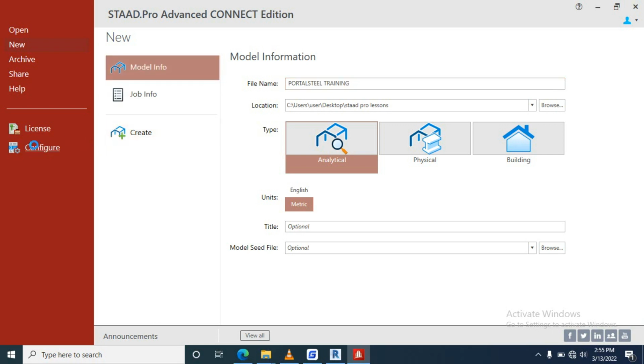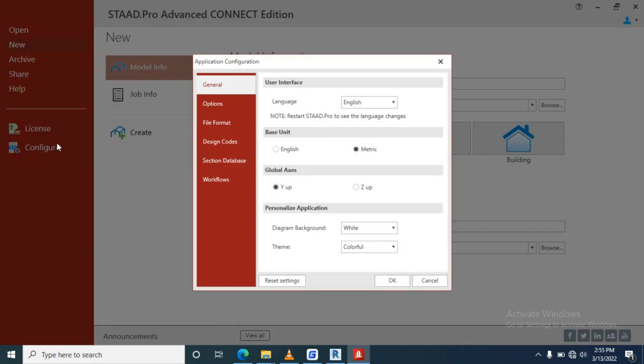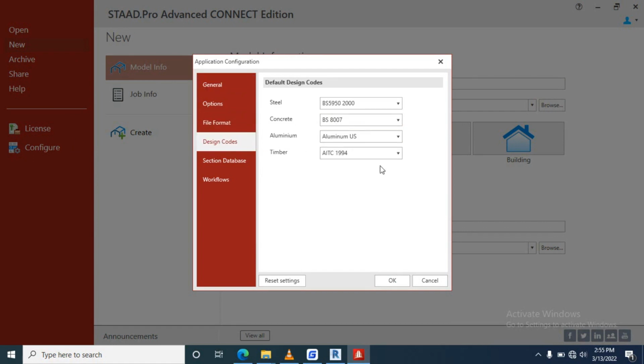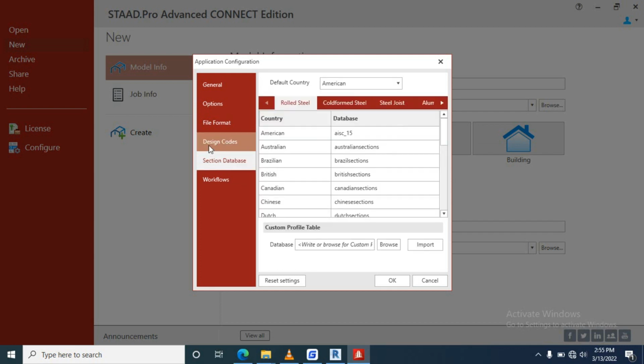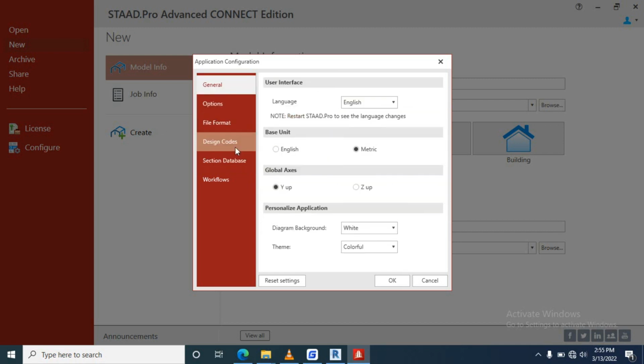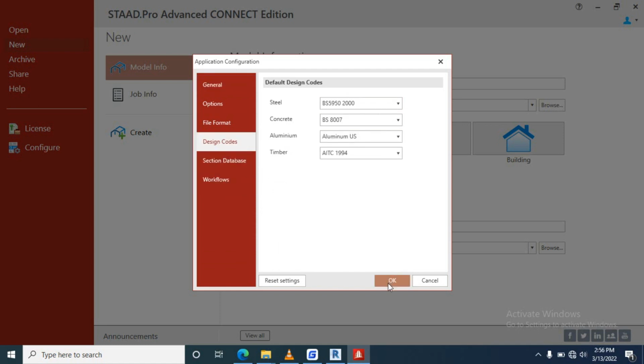geometry. Click this place, translational repeats. This is translational repeats. In the x direction, I want to have a span of 15 meters. Then I want to have a span of 14 meters. I'll click OK. I have two of them.